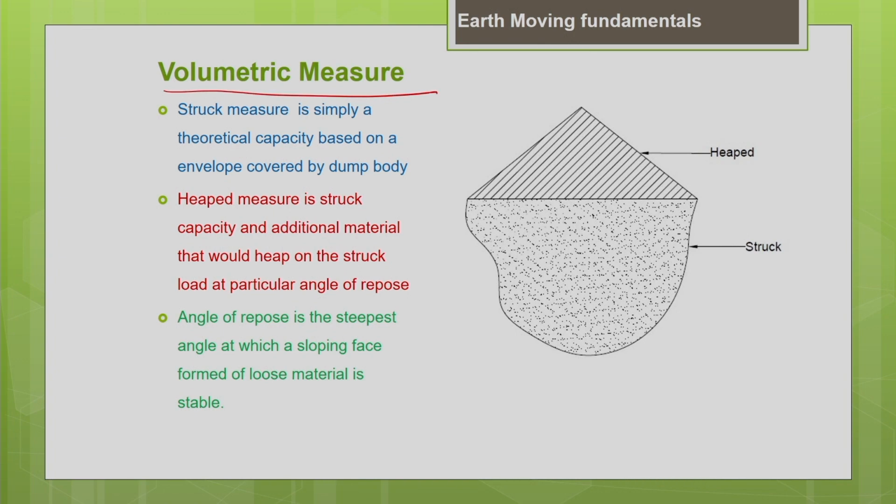the struck measure. Say, for example, you have the bucket of your excavator. You are going to excavate the load. You are going to load the bucket of your excavator. How do you express the volume of the bucket? Basically there are different ways to express the volume. Either you can express it on the basis of struck capacity or heaped capacity.